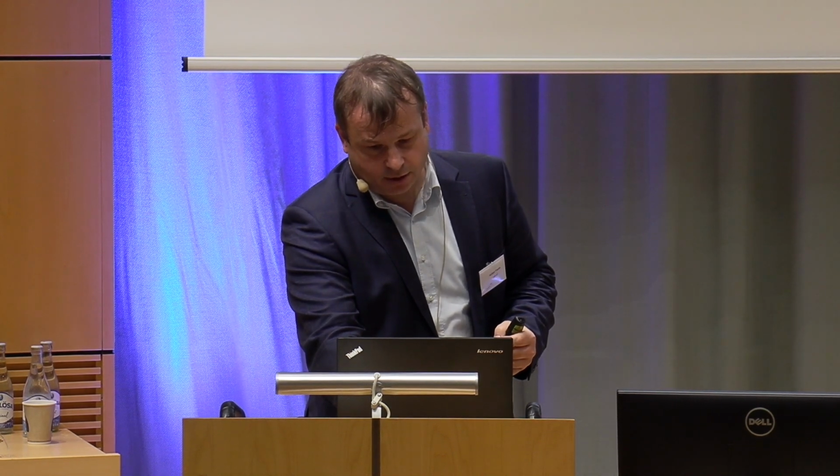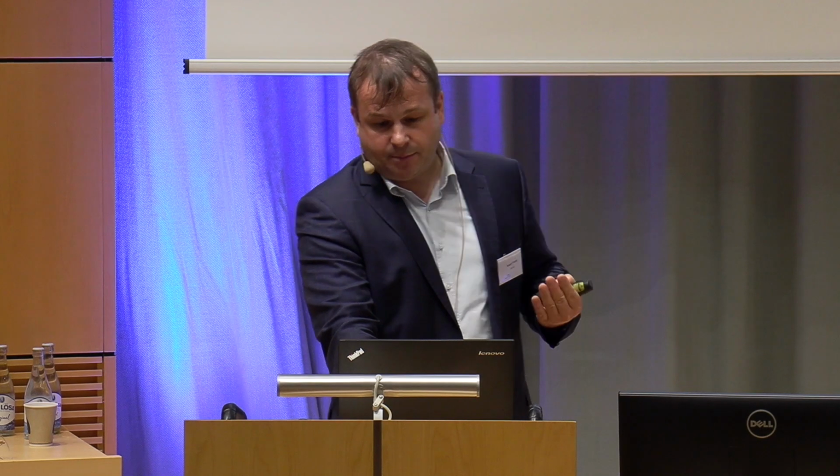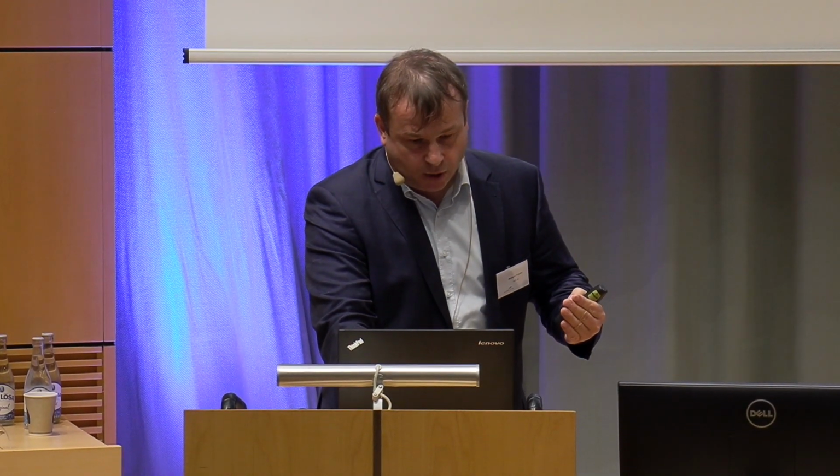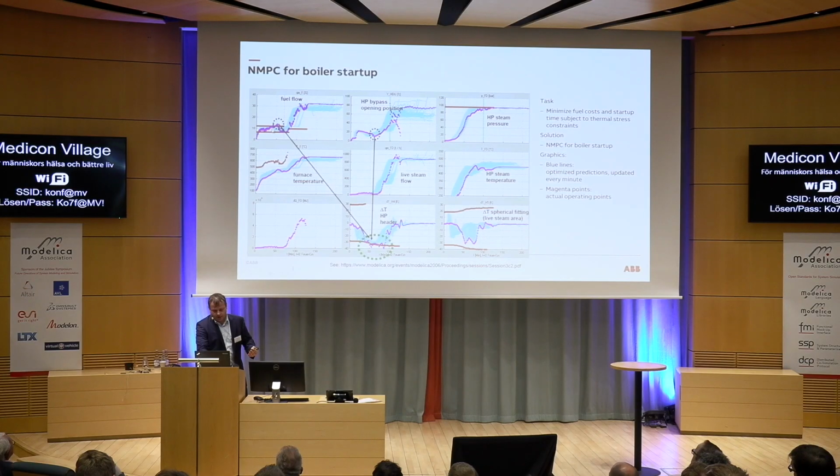So the NMPC has to control along the stress limit such that the power plant goes up as efficiently as possible. And here you see an example where the light blue lines show the predictions which we do at each minute for the whole startup. The dark blue points are measurements from the plant. Initially, we wanted to go up to 12% with heavy oil startup fuel, but the burners didn't do this at the beginning. Later on, they were overshooting.